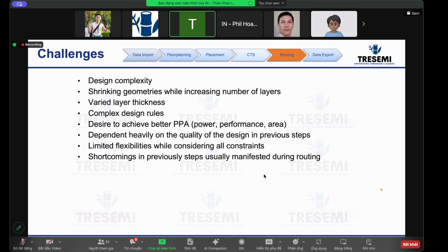Only a small percentage will not, because locally, something because of DRC means the detail router had to reroute. But because there's no congestion, more likely a high percentage of that global route will turn into real route.